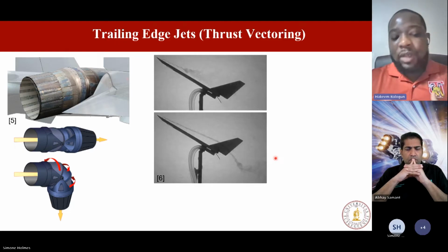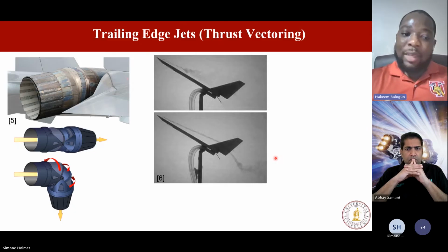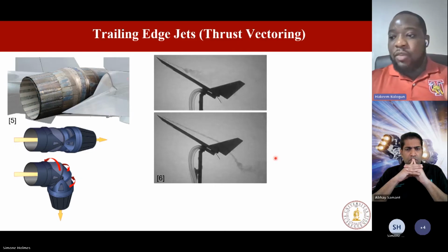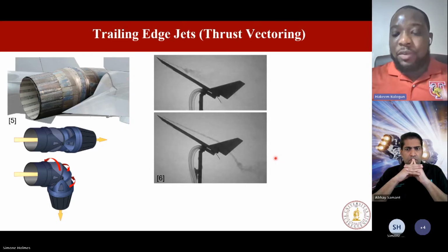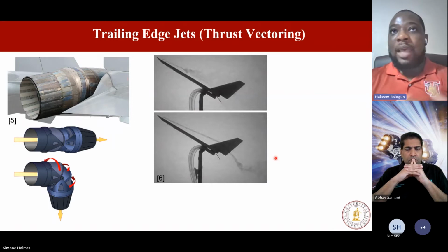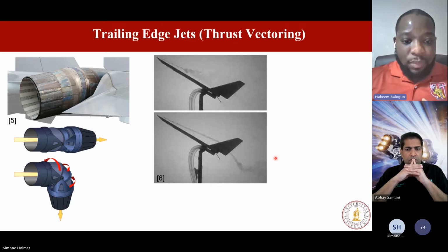This is important because vortex breakdown causes dynamic and static stability issues such as wing rocking, which are limit cycle oscillations of the delta wing along its roll axis. If you've ever seen an airplane's wings rock side to side, that is a result of wing rocking, and that's typically caused by vortex breakdown on delta wing type fighter jet flying wing configurations.